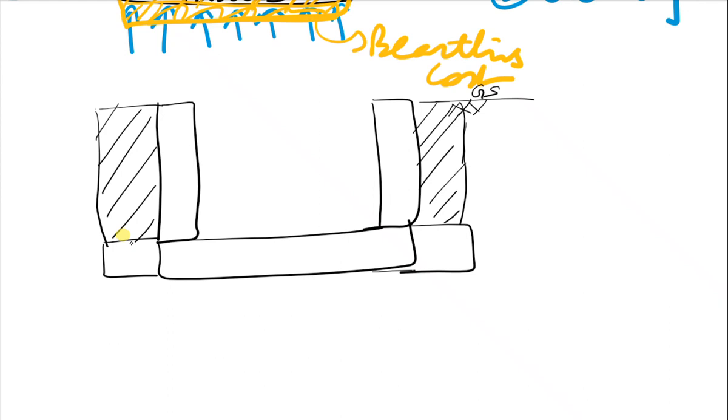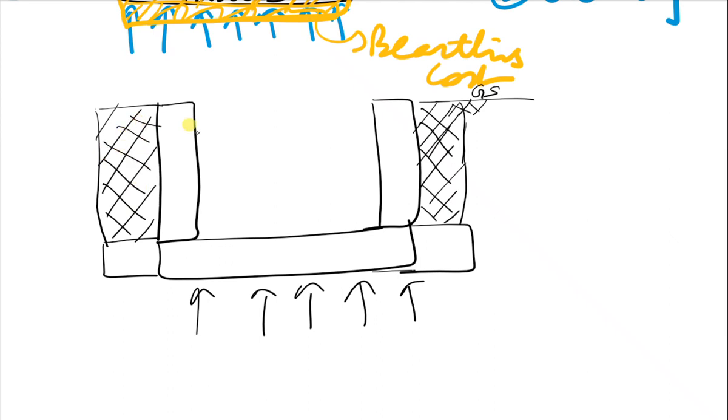So this soil is providing the counterbalance. When the tank is trying to uplift because of water pressure, the soil on the overhangs will resist it, right?